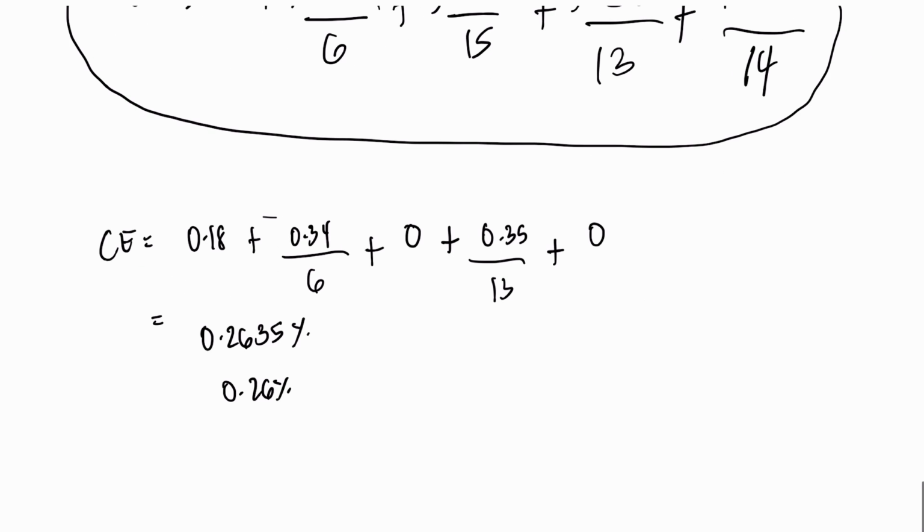So the threshold for the need for preheat is 0.45. If you exceed 0.45 equivalent carbon, that means you will need to have this material preheated at a certain temperature. The levels of preheat, as I've mentioned earlier, will depend upon the equivalent carbon that you have present in the material. This is just a recommended value or a preset limit for the equivalent carbon.